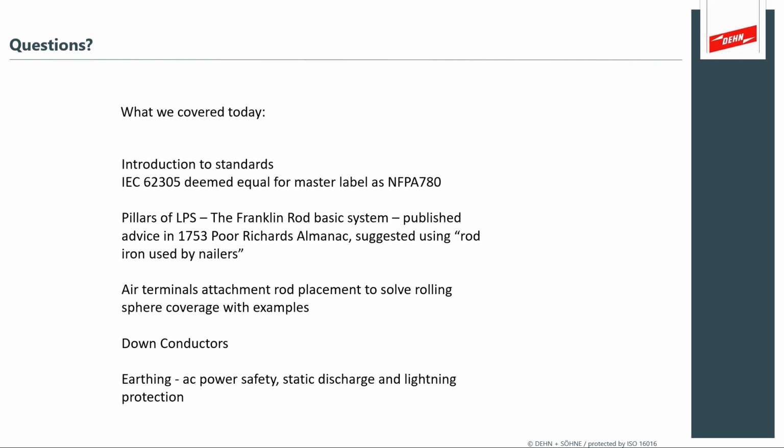And then when you see one that's an order of magnitude or more higher than its neighbor, you know there's a problem. So it's not necessarily that we've got a target value. It's that you want to use it as a measure of troubleshooting. And that we've seen to be very effective, because when somebody's got, maybe there's an earth ring and it's been dug up by a bulldozer, that type of problem shows right up, because that clamp-on measurement is orders of magnitude different than its neighbor, and then you know there's something different.